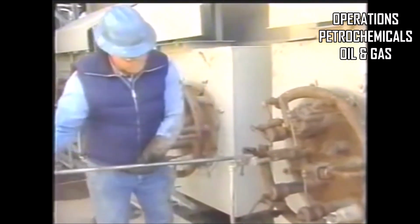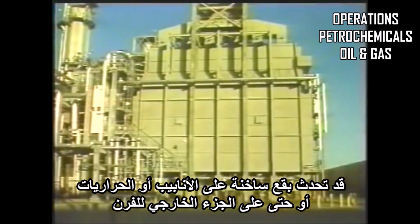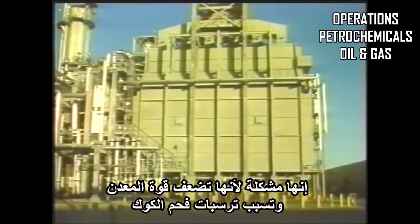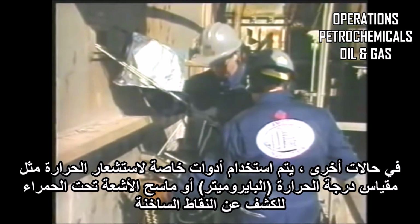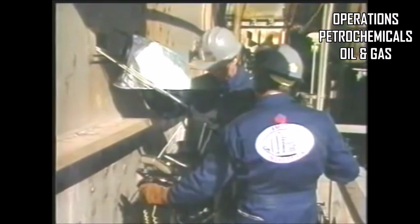cleaning or repair. A hot spot in a furnace is an area that has become overheated due to an improper distribution of heat or flame impingement. Hot spots may occur on the tubes, the refractory, or even on the outside skin of the furnace. They're a problem because they compromise the strength of a metal and cause coke deposits. Some hot spots can be detected with the human eye as a glowing red spot on the metal. In other instances, special heat-sensing instruments such as a pyrometer or an infrared scanner are used to detect hot spots.